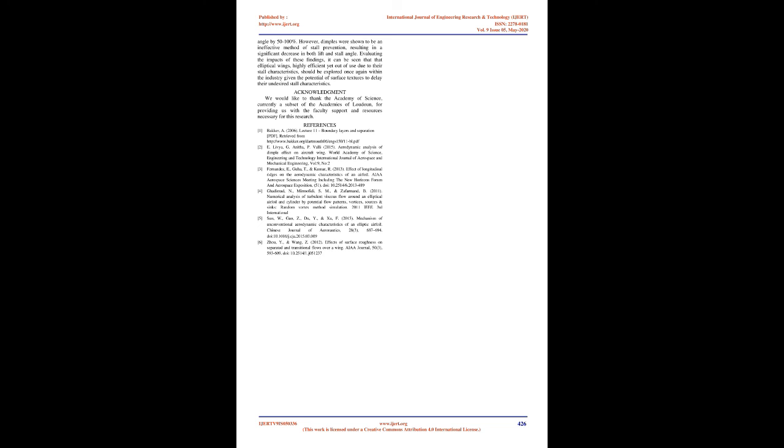In a transient flow analysis, time is a factor that can be used to understand the time dependencies of stall on wings modified by surface textures relative to a reference wing. Secondly, the surface texture geometries, for example the radius and shape, can be modified to produce higher stall angles and lift values on elliptical wings. A wing, even if modified, must be able to handle the stress of flight, and thus a structural analysis would be paramount to such a wing's applications to industry at large.